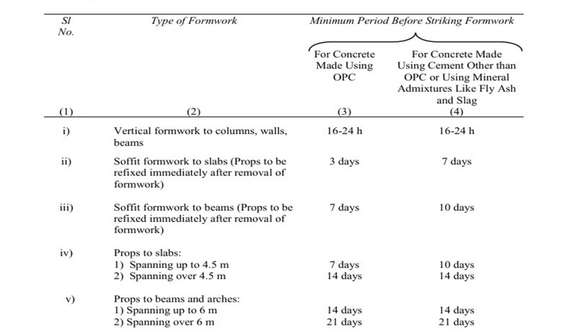And props to beams and arches, spanning up to 6 meter, that is 14 days for the OPC and 14 days for other than OPC. Spanning over 6 meter, 21 days for OPC and 21 days for other than OPC.